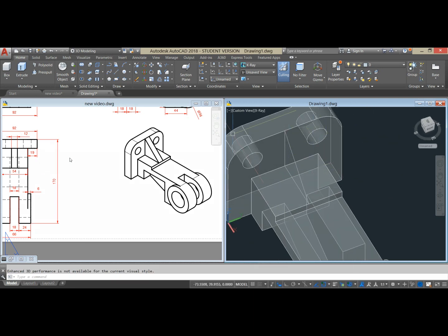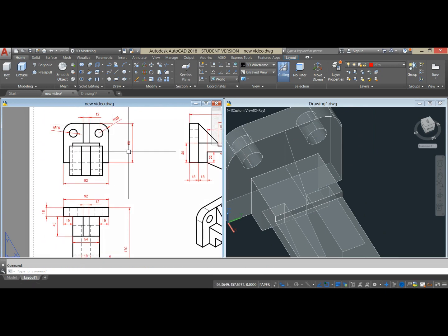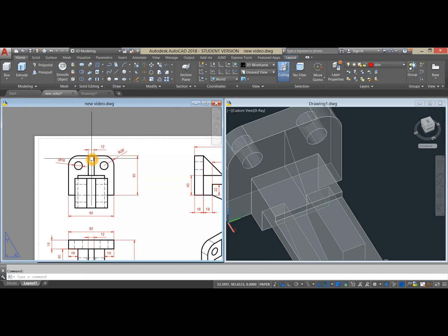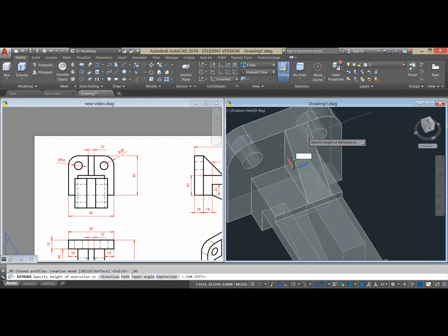The thickness for that is, which is this one. This one is this one. So highlight that. Extrude for 6 units on the other side. And then just press pull the other side for another 6 units. Now the total is 12.